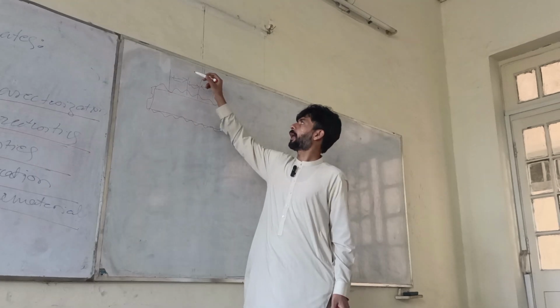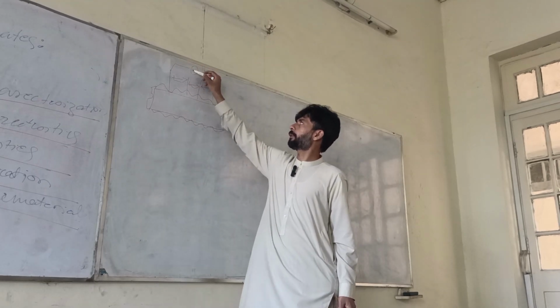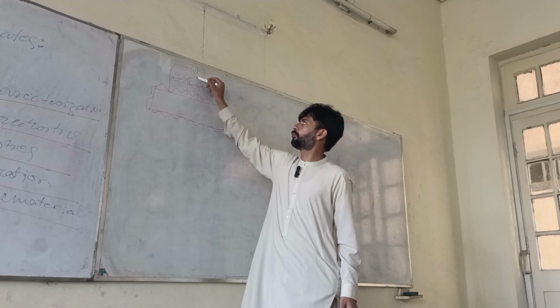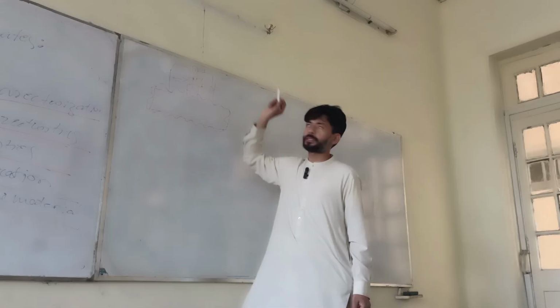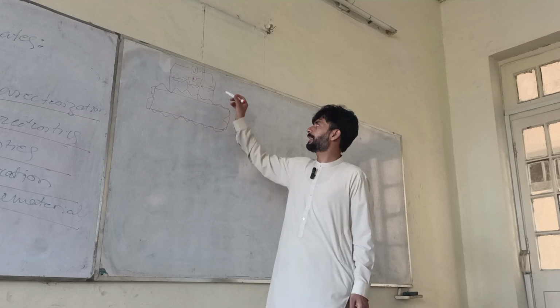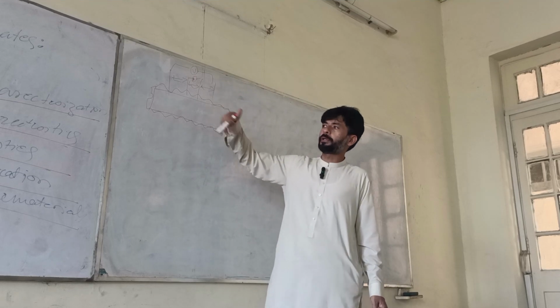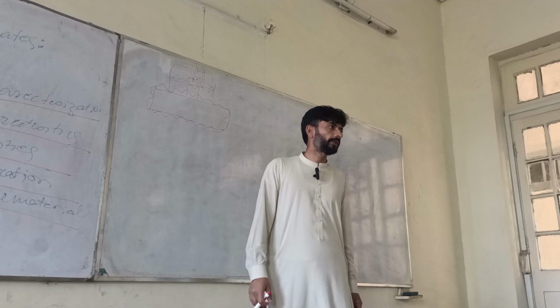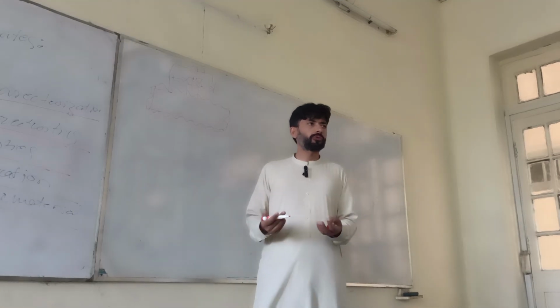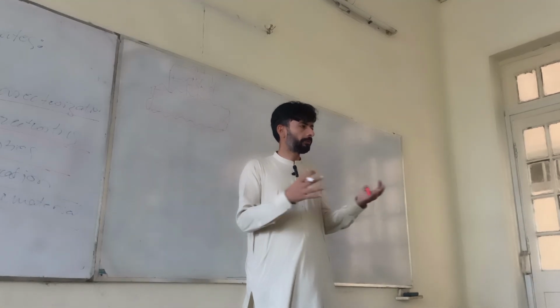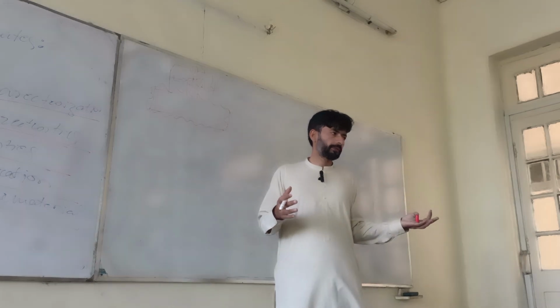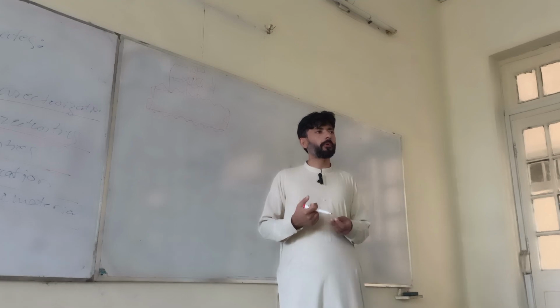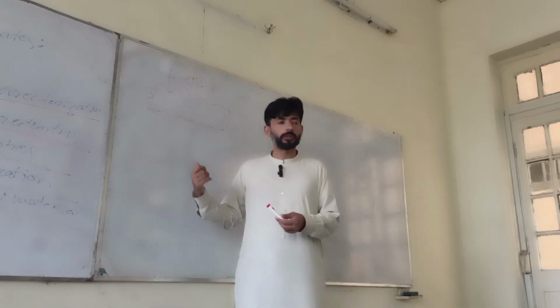Okay? And these two probes usually apply voltage and those measure the current. In this way, the probe resistances are eliminated from our measurements, and also the area, the geometric factors are eliminated. Okay? So if you face such kind of problem, then you have to use what?